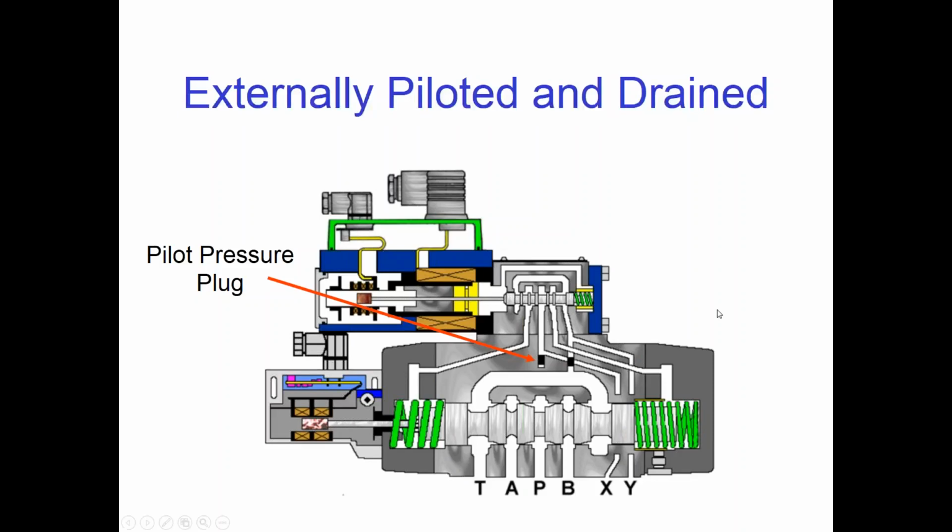If it's meant to be configured for internal pilot and drain, and it comes back with these plugs installed, then when we install it, it's not going to work. We won't be able to get any pilot pressure, and we won't have anywhere to drain the pilot valve.